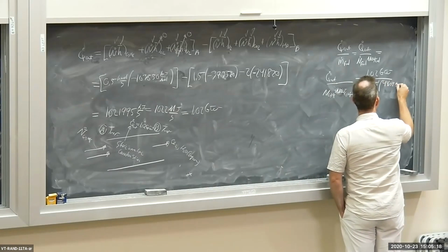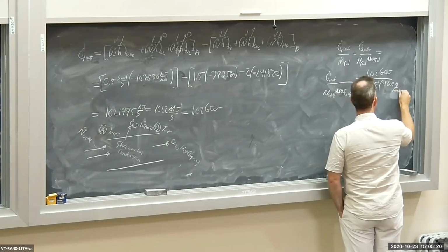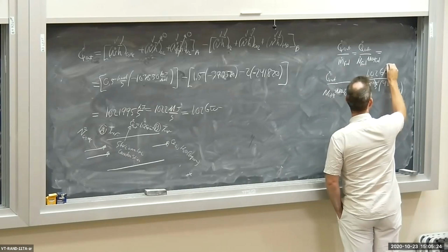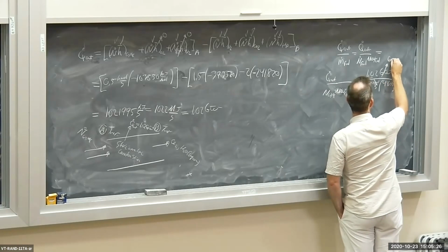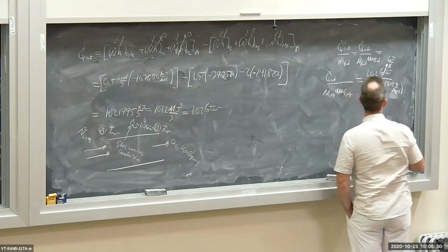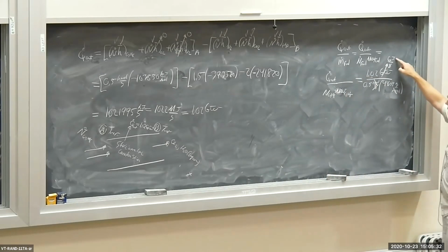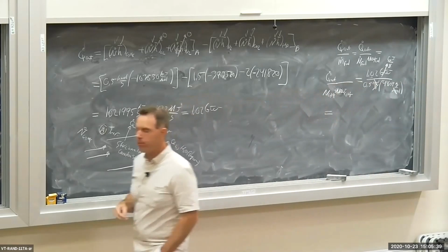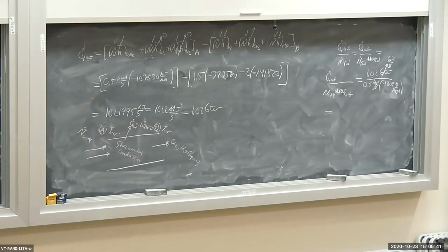44.09 kilograms per kilomole. So the unit here is going to be, the kilomoles will cancel out. The gigawatt is a gigajoule per second, so the seconds cancel out. And I get gigajoule per kilogram. This is going to have a unit of a gigajoule per kilogram.